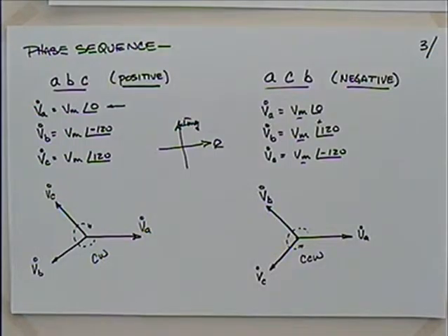That's one of the good things about three-phase and the bad things about three-phase. It is very easy to change the direction of something. Single-phase motors, sometimes you plain can't change the direction of that motor depending on how that motor is made. But with a three-phase motor, you can always change the direction of it, and sometimes it's way too easy.